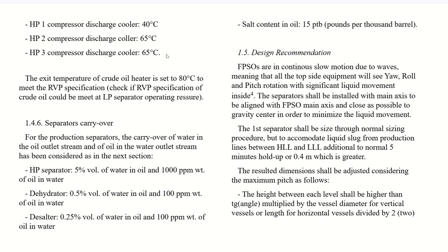Then discharge temperatures of the coolers, then separator carryovers. These also need to be added into the simulation files. It talks about 5%, 0.5%, 0.2%, which is the carryover of liquid in the gas system, gas phase.